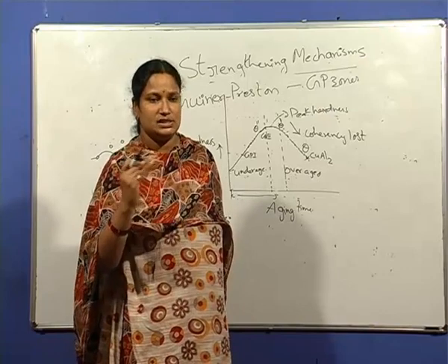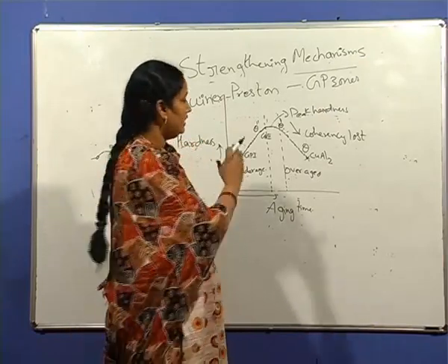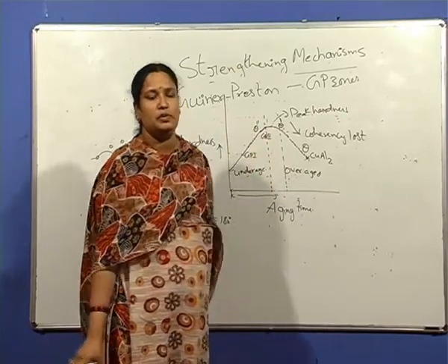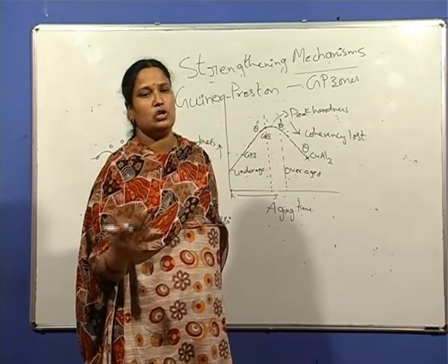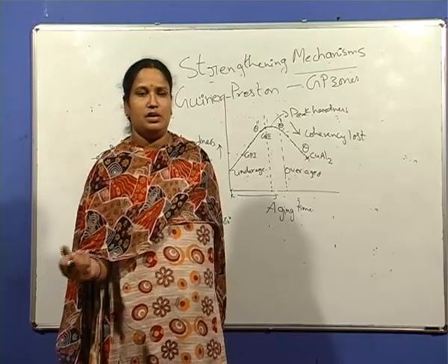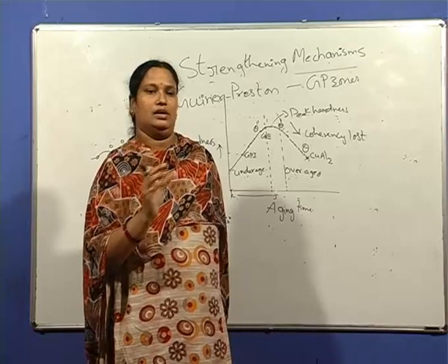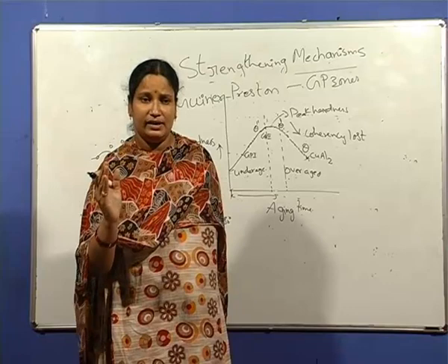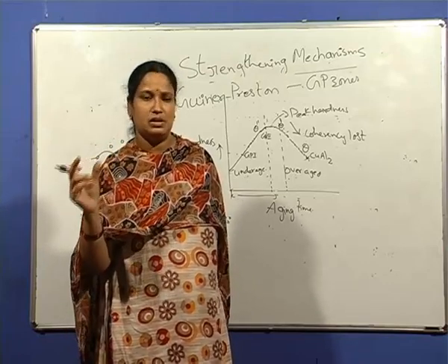So these are the various transition phases that are observed in the case of aluminum copper alloy, whereas generally the same is not followed in the case of other precipitation hardenable alloys. There we have the formation of a coherent precipitate with increase in aging time, and then with still further increase in aging time, the coherency of the precipitate is lost.